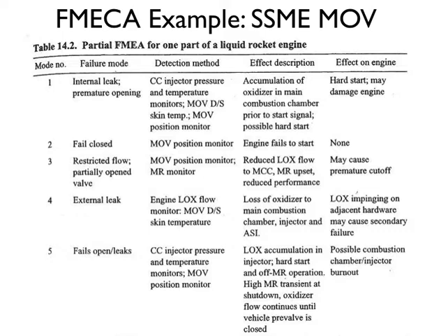The effect description: accumulation of oxidizer in main combustion chamber prior to start signal, or possible hard start. And the effect on the engine is hard start or may damage engine, which is a little bit vague. Okay, and so you can kind of see the style of this worksheet.